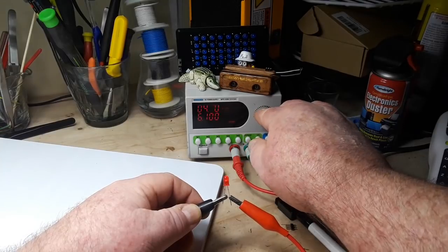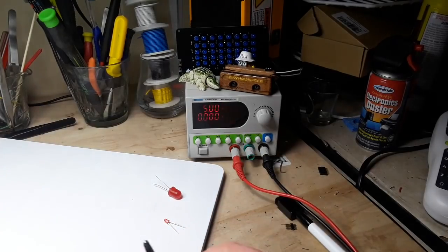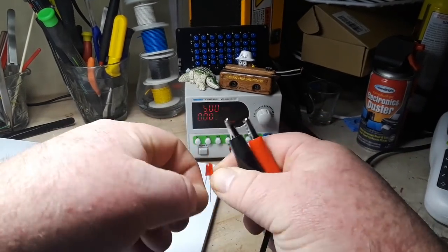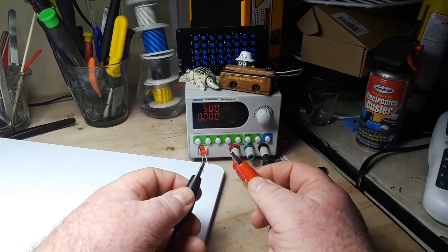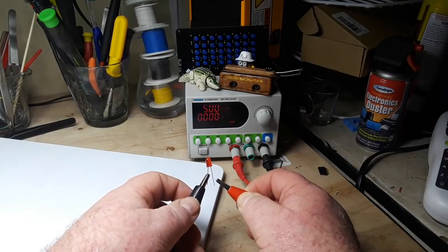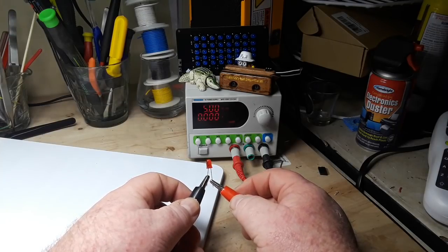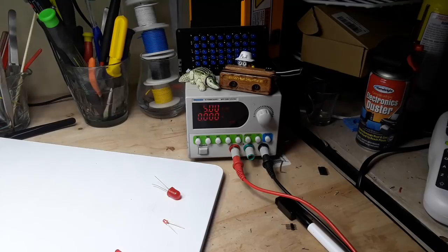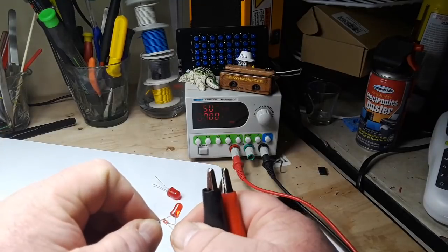Oops. 5 volts and she's dead. So let's try another one. I'll grab another red LED out of the package. And we'll do the same thing. 5 volts is still considered low voltage, by the way. But no current limiting. It's probably going to blow right away, right? 1, 2, 3. There. You got a blip, and that was it. Nothing else.